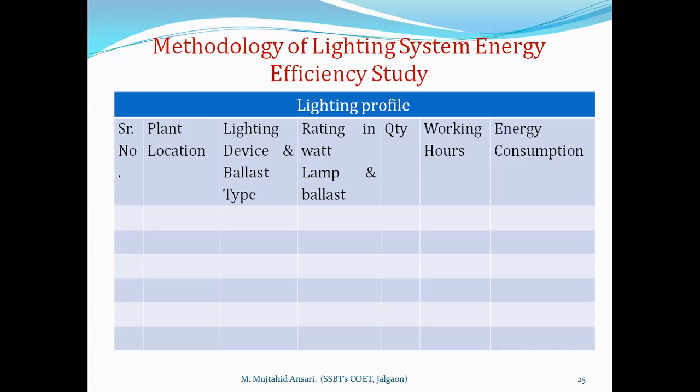So it is recommended that in addition to the discharge lamp, we provide some tube fittings or fluorescent lamps because they come on quickly. As soon as the power resumes, some of the task lights start first, and movement becomes very easy, because it is quite difficult in complete dark.